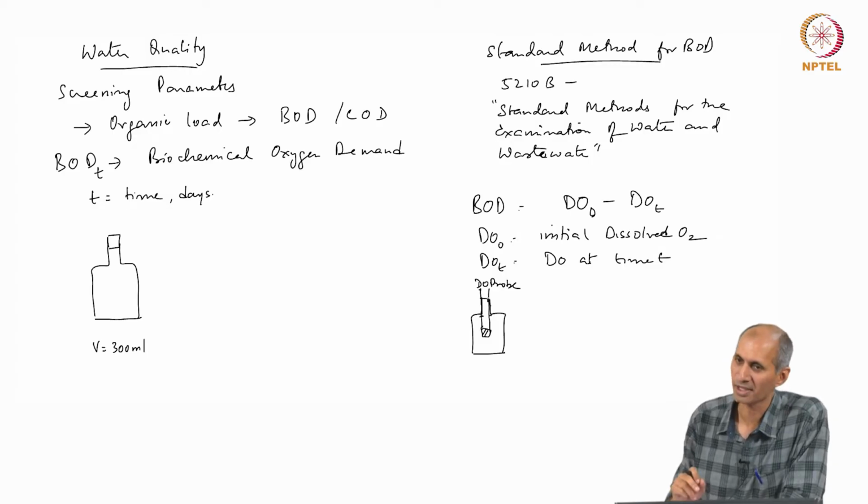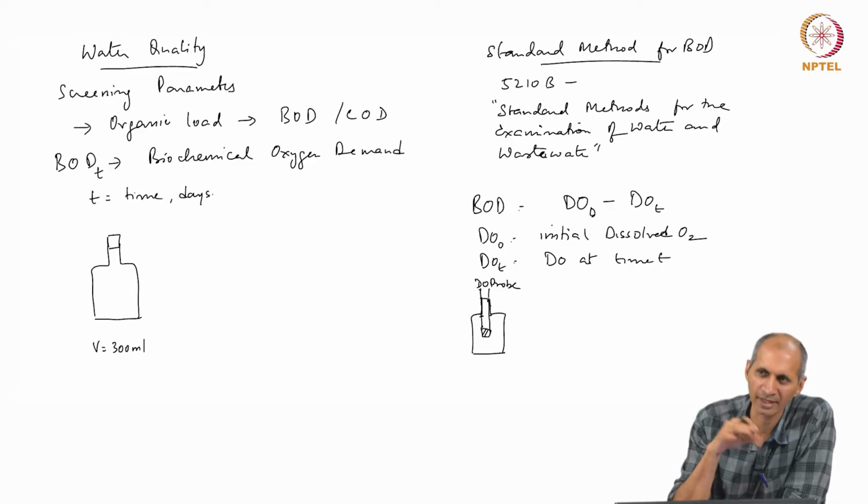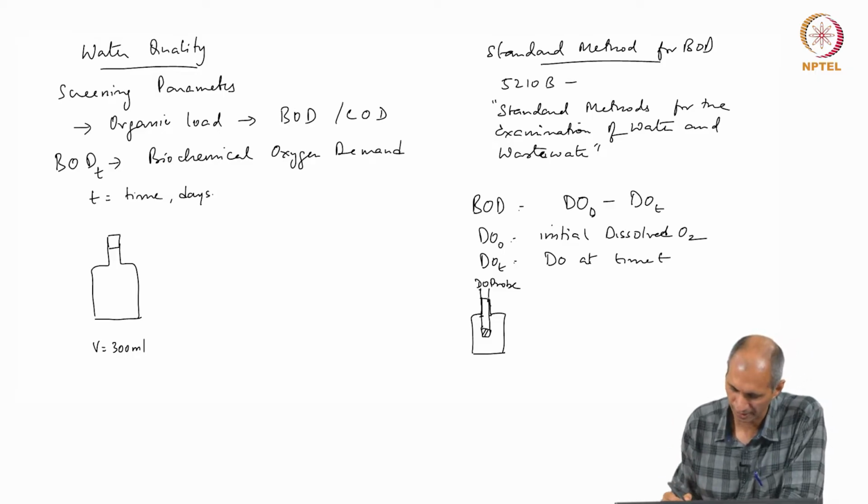The volume is not really that important here. The only way volume is important is if it creates a head space, then it is a problem, because oxygen will go and equilibrate there, and the available oxygen for use in the BOD is not enough.